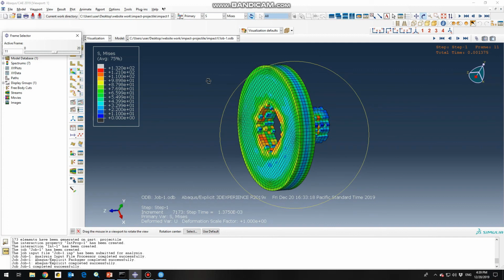So as you can see guys, it's fun to define and use shear failure and all such things. Suffice to say, the key points of this simulation are in the property section. You need to use model edit and put the shear failure in very carefully, and then when you want to define the mesh for circular plates, as the elements should be deleted after the impact, you need to choose yes for the element deletion.